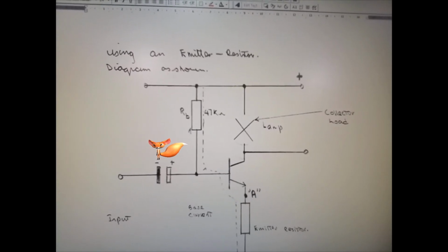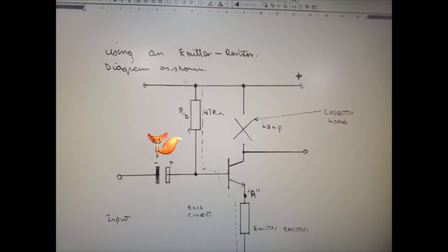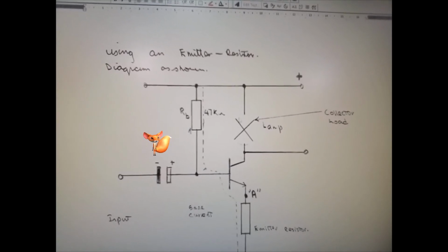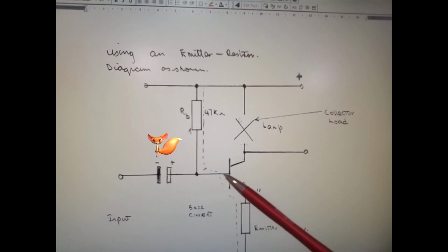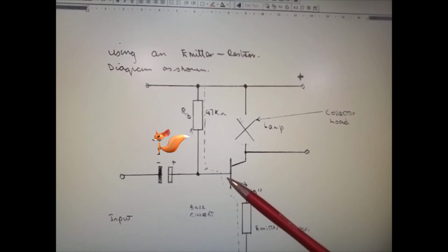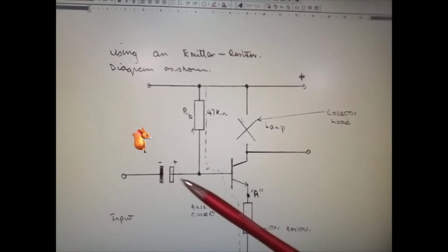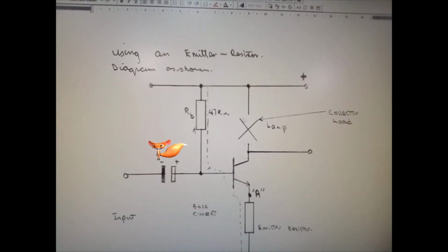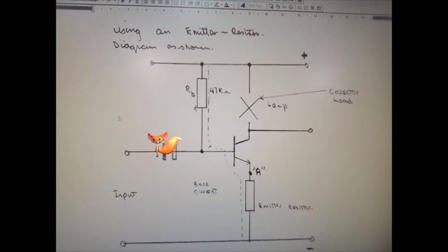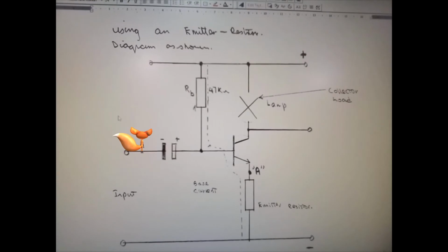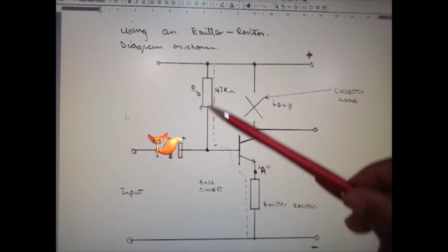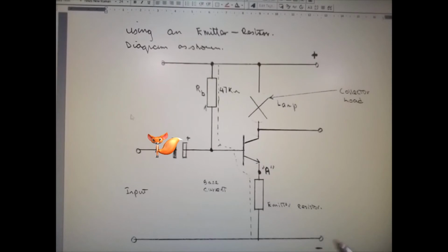And again, looking at what we've just said, this is not just showing you how it has affected your circuit. Okay, and RB here in this case is 47k, and that is controlling the current to the base of your transistor. Okay, and remember here you will just be inputting your signal, and your signal may come from a signal generator or whatever you decide to input, but this would allow you to control the current at the base.